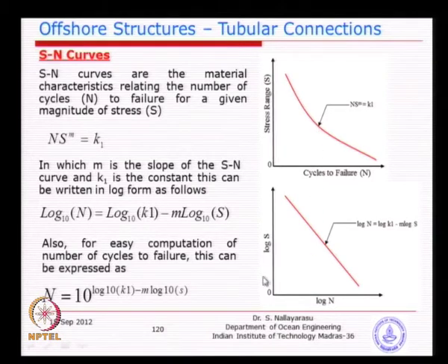Now, when you plot the same data on a log axis or log plot paper, I think you might have seen this in your mathematics course; normally you have a log paper just for convenience. The characteristics are such that when you plot the SN curve in the log graph, it becomes linear. So, we can write this in terms of a log equation. Basically, that is what we have done.